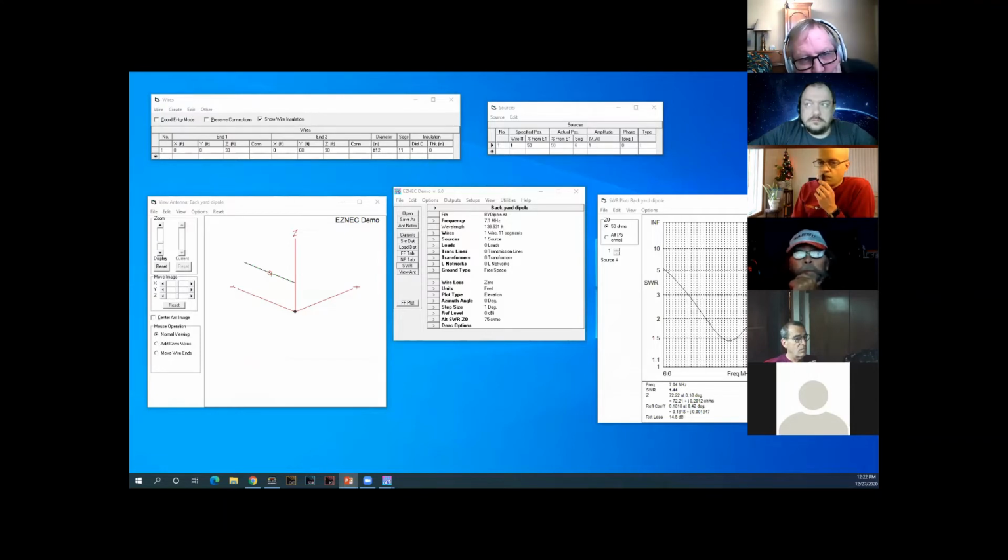Any questions so far? Are you able to keep up? Okay. Now, just to show you the effect and the power of this program, let's go back up here to this insulation type. So far, we've been using bare wire. We've specified bare wire because 1 is the dielectric of free space and 0 is the thickness of your insulation.